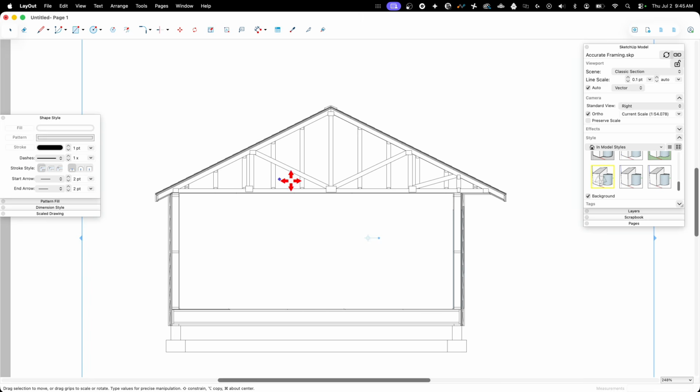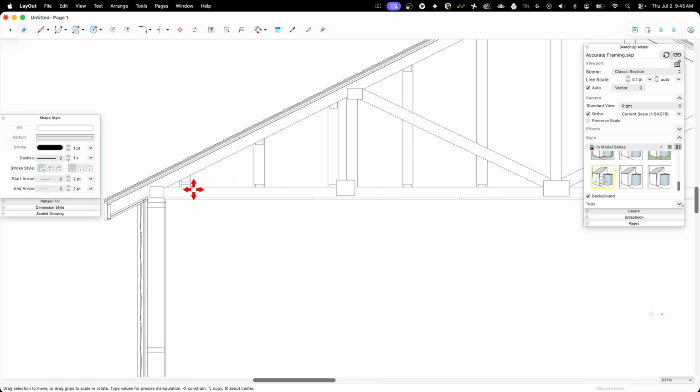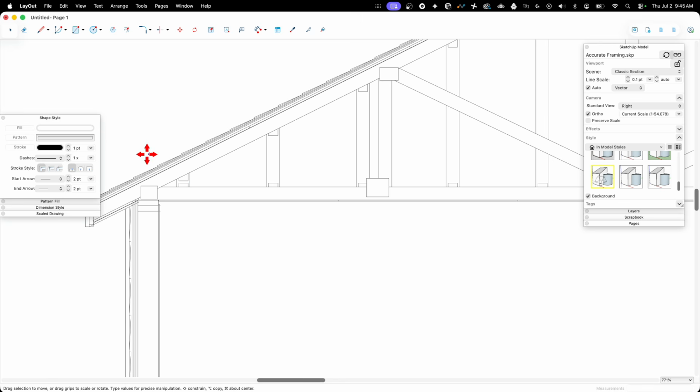So again, depending on how I want to do this, what I could do inside of SketchUp is come in and actually turn that piece off. I could go grab that specific piece, turn it off, and then save my section cut scene with that turned off. I didn't do that because I wanted to show you the limitations here, but that is probably the close. This is theoretical.